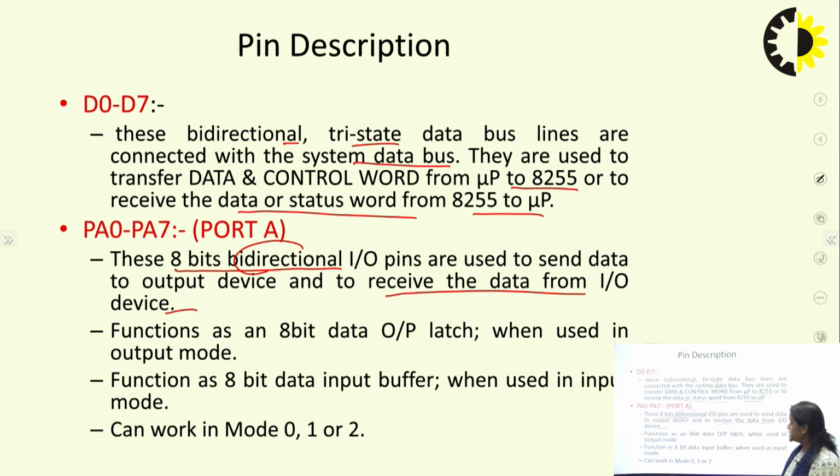It functions as an 8-bit data output latch when used in output mode, and as an 8-bit data input buffer when used in input mode, and it can work in mode 0, 1 and 2. So, port A can be used for mode 0, mode 1 and mode 2.